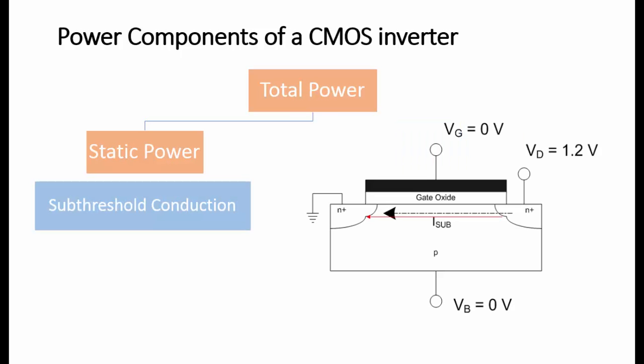We start by explaining the static power consumption, which derives from the transistor channel length as well as doping level and gate thickness. In reality, all MOSFET transistors leak current between the source and the drain if there is a voltage potential across that source drain channel, even if the gate voltage is in off state.